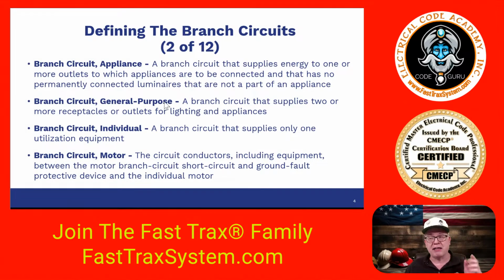So what is an appliance branch circuit conductor? Well, a branch circuit that supplies energy to one or more outlets to which appliances are to be connected and that have no permanently connected luminaires that are part of the appliance, okay? So you've heard of small appliance branch circuits, okay? Required a minimum of 2 in that application in 210.11(C), right? So those are appliance branch circuits. They're designed for appliances to be connected to those circuits, right?